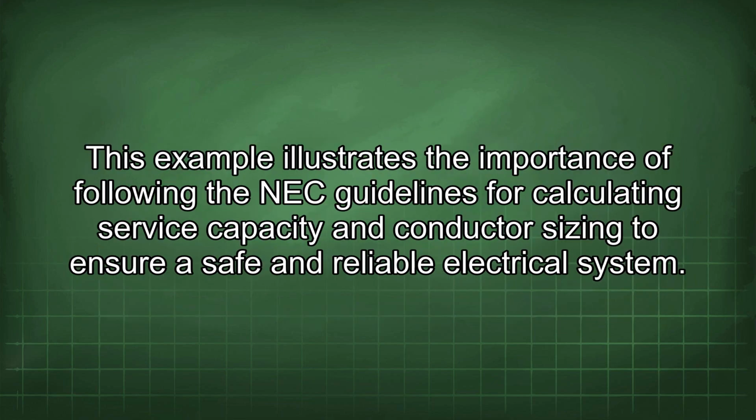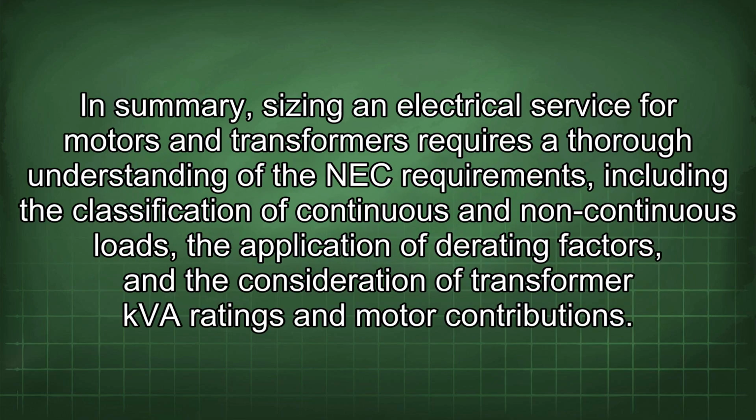This example illustrates the importance of following the NEC guidelines for calculating service capacity and conductor sizing to ensure a safe and reliable electrical system. In summary, sizing an electrical service for motors and transformers requires a thorough understanding of the NEC requirements, including the classification of continuous and non-continuous loads, the application of derating factors, and the consideration of transformer kVA ratings and motor contributions.